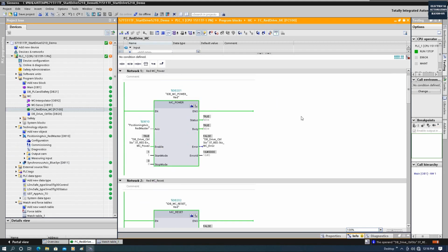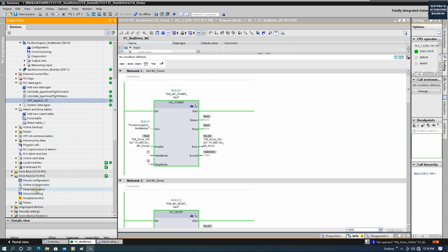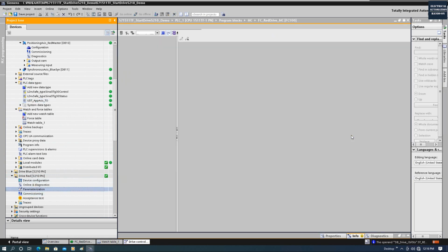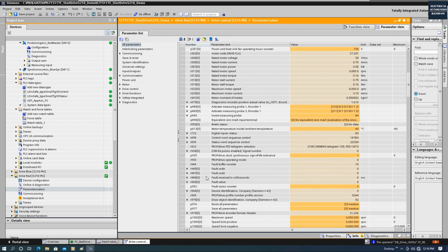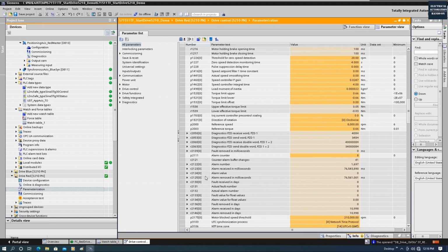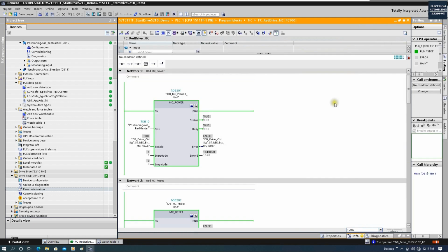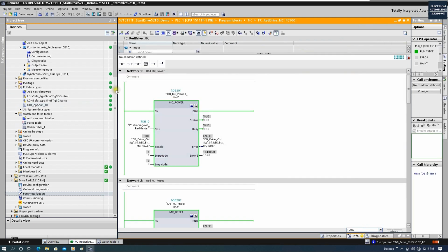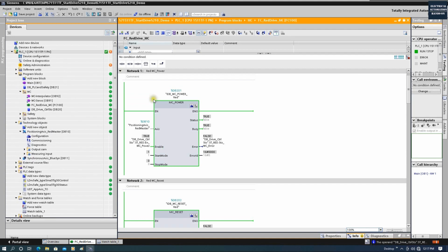Before we start to run this motor, let's double check this parameter from this drive. If we go to the drive parameterization, let's check P2175. This P2175 is now running at the default value, which is 0, so we enable this feature, the motor blocked speed threshold. Also from the TO, everything is normal, like the monitoring, following error; all those monitoring are enabled.